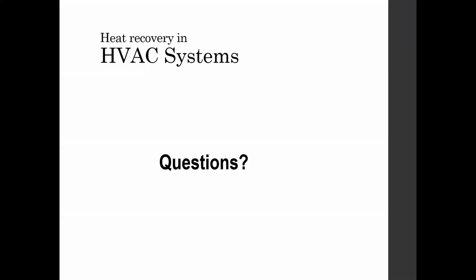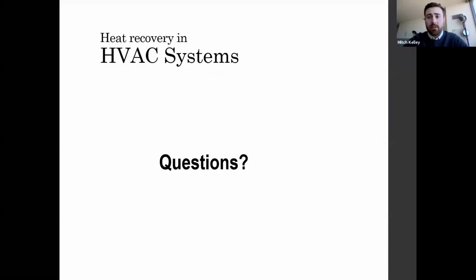All right, any other questions, please send them in. We've got one saying you mentioned 150-degree temps can be reached. How high? I assume these were screws. Yes, that is a screw example. You can get 150, almost 160, off of a screw chiller. But again, the key thought is, are you using more energy to operate the chiller at that lift rather than just using something else? Are you actually gaining anything by doing that is really the question.